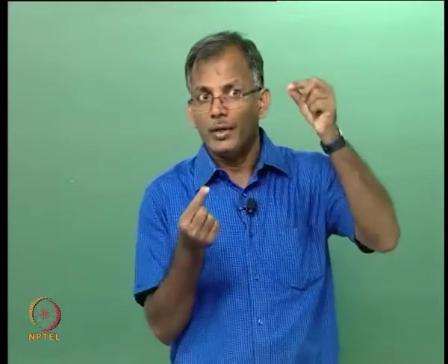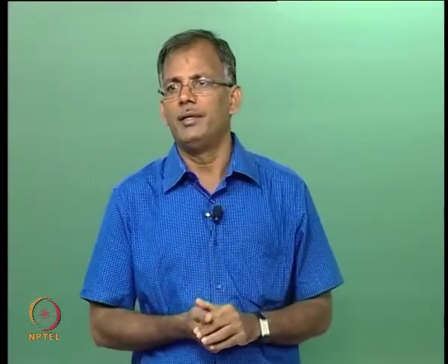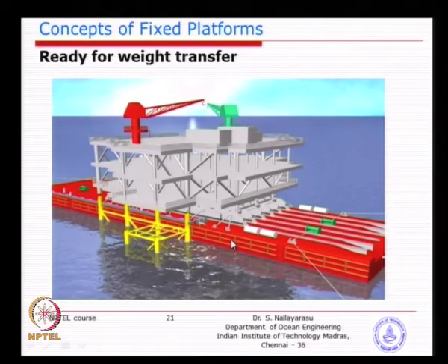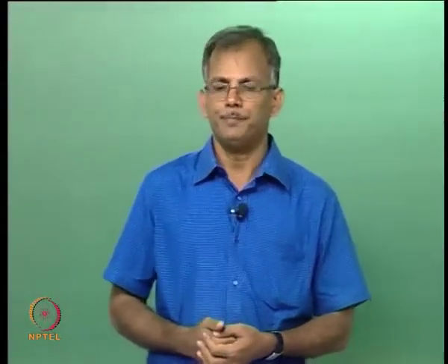You might see that the tidal cycle is about 8 hours, so you will have only a limited time during that particular period. So, you will have to fix up, do this operation and get away, because if you do not get away, what will happen? The rising tide will take the barge up and then hit it back. You understand the idea, no? Even though you have installed, if the barge remains there, the barge will just go up and then hit against the structure. So, you will have to remove it as quickly as possible.